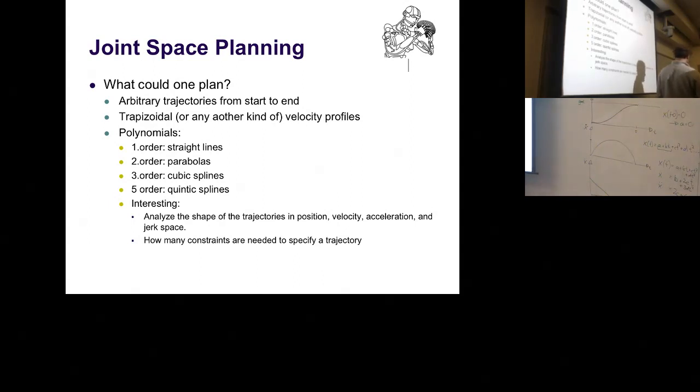Okay? So I'm using the whiteboard, but it's just a line and just jumps back. It still has these jumps at the beginning. The velocity now has become quite nice. It's pretty. This is still a little bit annoying. But these third order cubic polynomials are one of the representations people like to use a lot. Since what is nice about it, and I'll show you in a second on a slide, you can get the boundary conditions for start and end position and start and end velocity coded very nicely.